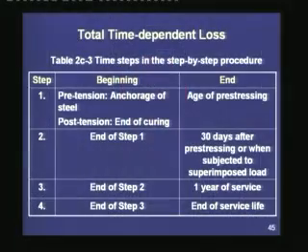The third time step starts from the end of the second time step, that means after 30 days after pre-stressing, to the first year of service. That means again our third time step considers the loss of pre-stress for the first service year, because it has been found that creep and shrinkage can be substantial in the first year of the service, and hence we need to recompute the pre-stressing force after the first year of service.